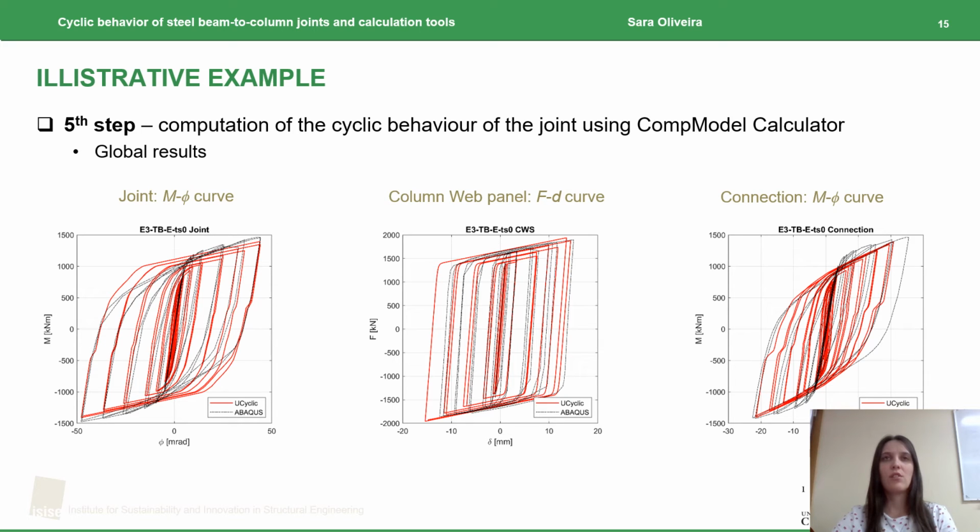These figures show the bending moment-rotation relation for the beam-to-column joint computed from ABAQUS's finite element model and with Cyclic, showing in general a good agreement. The main disagreement in the moment-rotation curve of the beam-to-column joint is the slope of the unloading branches for a bending moment close to 0, for both sagging and hogging moments. The bending moment-rotation computed with Cyclic shows high pinching, but the bending moment-rotation computed with ABAQUS does not.